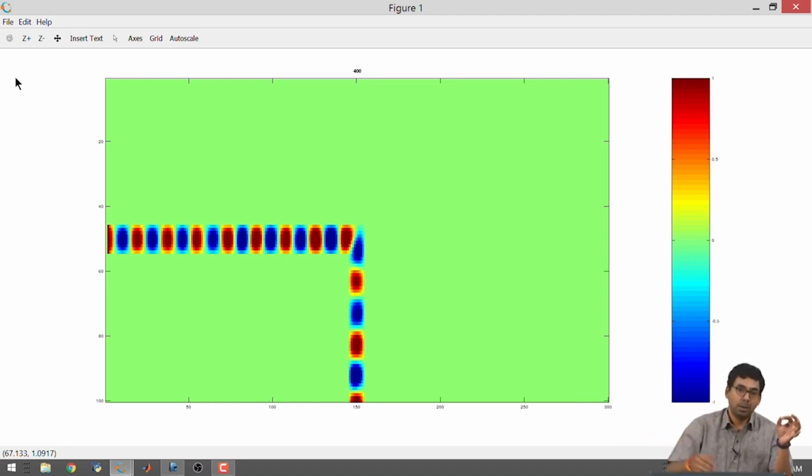You can push this to one more extreme and say that you put the source right in the middle of a metallic box. It is covered with plate on all 4 sides in the cross section, 2 sides in this way. In those cases, the energy will not be able to leave the box. It will keep on bouncing back and forth, and it will keep on being present inside the box. So, you can use the analysis that we had, and in several books there is some treatment about cavities, resonators, etc. These are all extensions of the same concept.